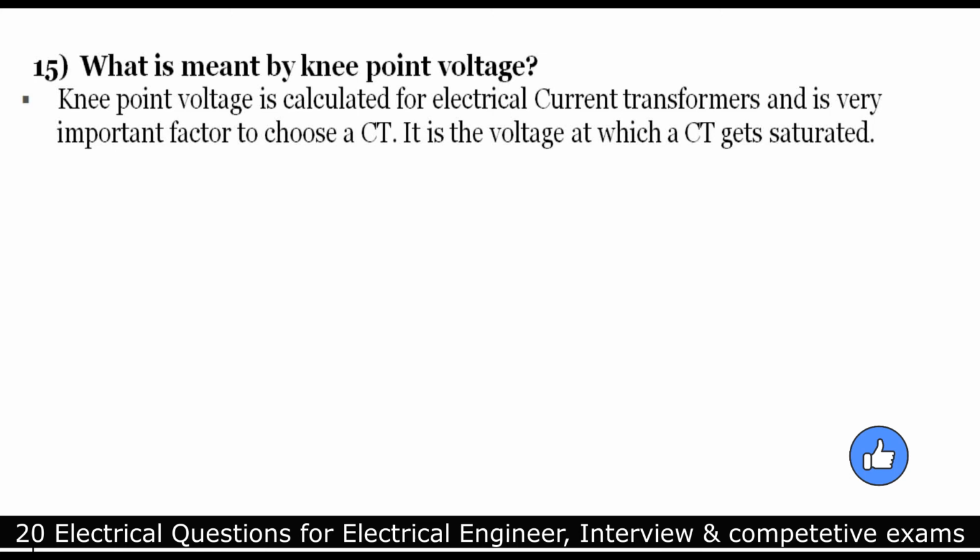Knee point voltage is calculated for electrical current transformers and is a very important factor to choose a CT. It is the voltage at which a CT gets saturated.